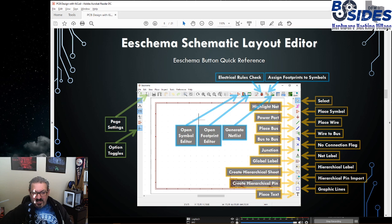You have a bunch of option toggles here. These are things you can toggle on and off to either change what cursor you're using, or to change how something is working, or to change how you're viewing something. And then across the top, we have several tools that we can use. We have our symbol editor that we can launch right from here. Same thing with the footprint editor. We have a button that'll allow us to generate a netlist file when we're ready.